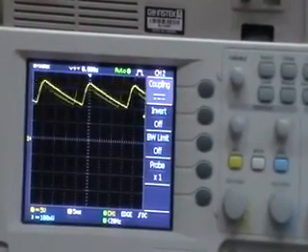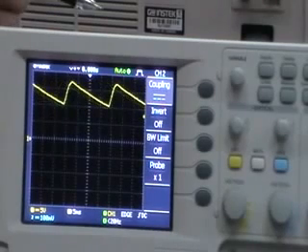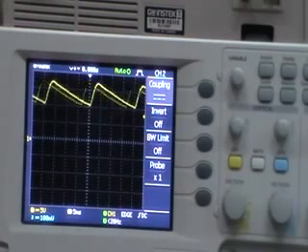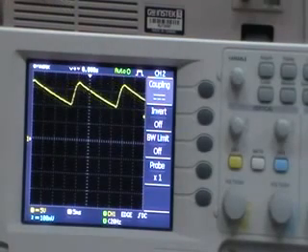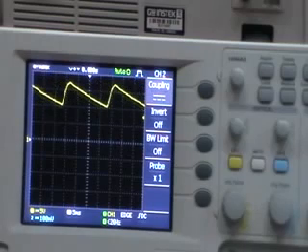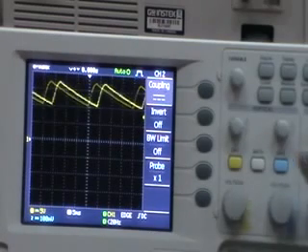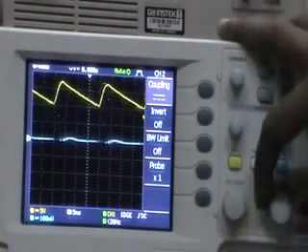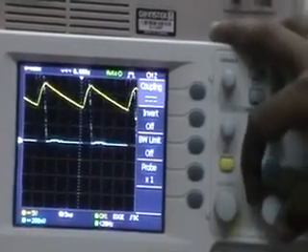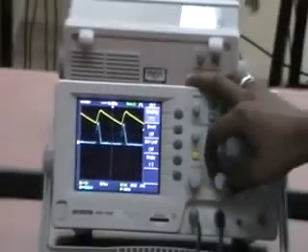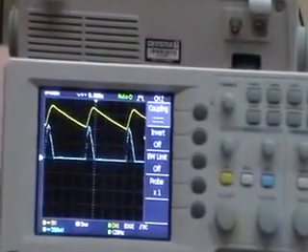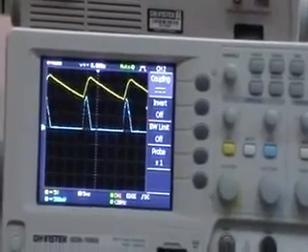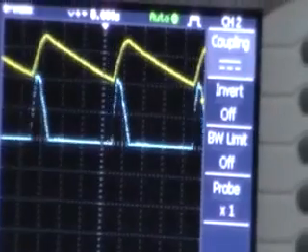The other thing that we have to find is the diode current waveforms, by using the channel 2 interconnections. So these are the waveforms. This is the diode current waveform, and we can find the peak value of the diode current easily from the diagram observed in the DSO.